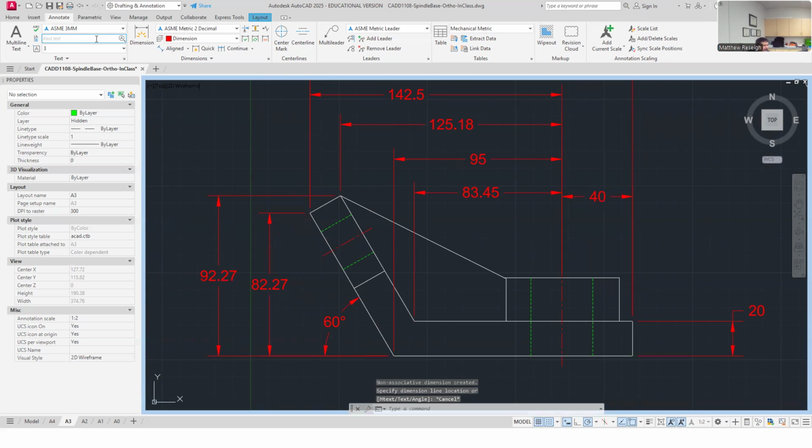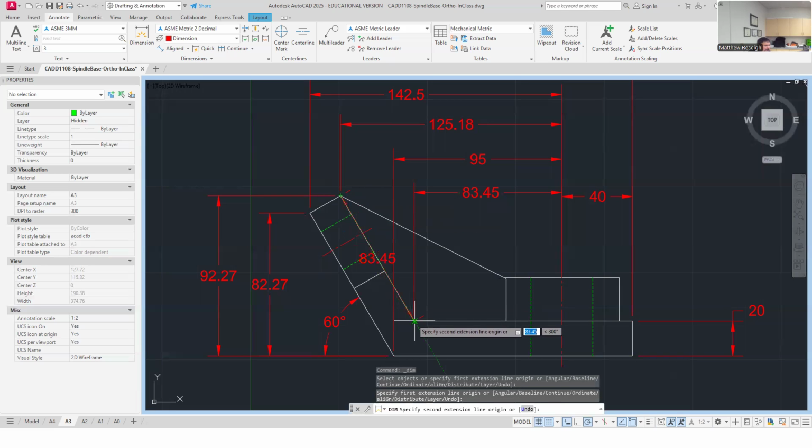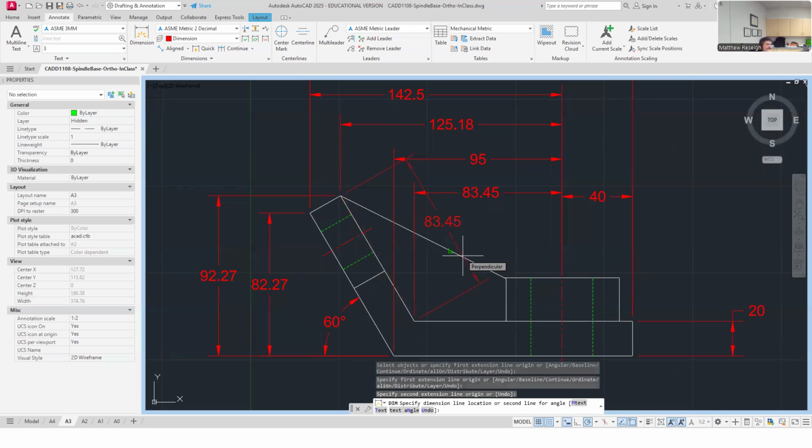And the one that they might actually want, if this was an actual bent part, and this is into the weeds a little bit about manufacturing, is they'd probably want to know the ID dimension of this actually. They may want to know where to measure that part. And so when the press brake comes down and hits that spot, that it's starting from this dimension. Usually when you're bending stuff, the operator is looking at the inside of the bend, not the outside of the bend when you're running that equipment. But that's an in the weeds thing for manufacturing.